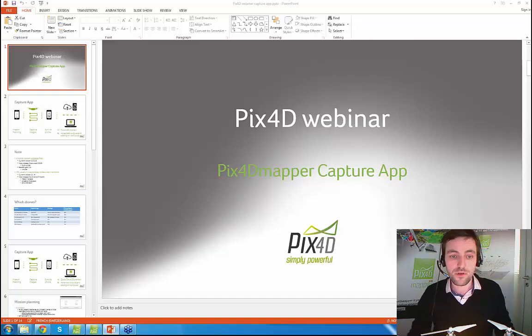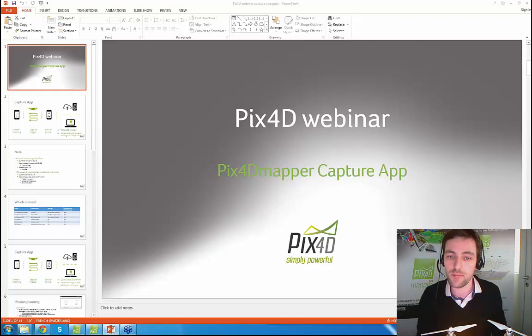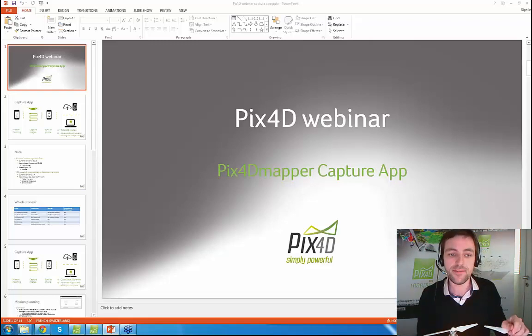So the grid mission. The reason we did this grid mission is because with a grid mission, you can be certain, like 99.9% of the time, that you're going to get accurate and reliable results. Because to get accurate and reliable results, it's mostly a matter of consistent overlap. And by doing this grid and the settings we set in the grid, so the grid is by default a 50 by 50 meter grid, and we take images every few seconds in such a way that we know that the overlap on the ground is very, very good. And this is basically optimal for most of the environments.